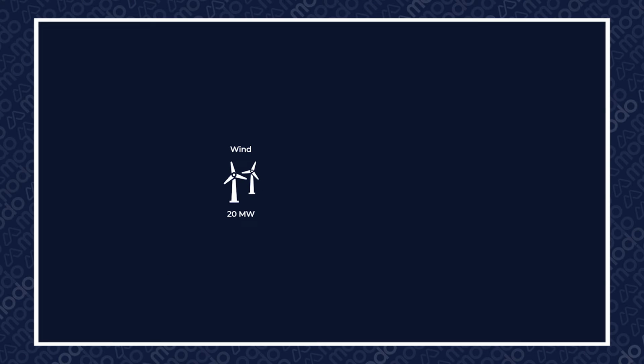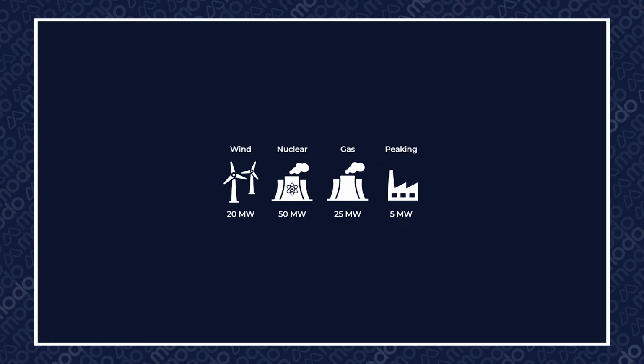As with most things, the best way to explain the generation stack is with an example. Let's create our own mini energy system and construct the supply and demand curves that govern the wholesale market. In our system, we have a small selection of generation units: 20 megawatts of wind, 50 megawatts of nuclear, 25 megawatts of gas turbines, and 5 megawatts of peaking plants.